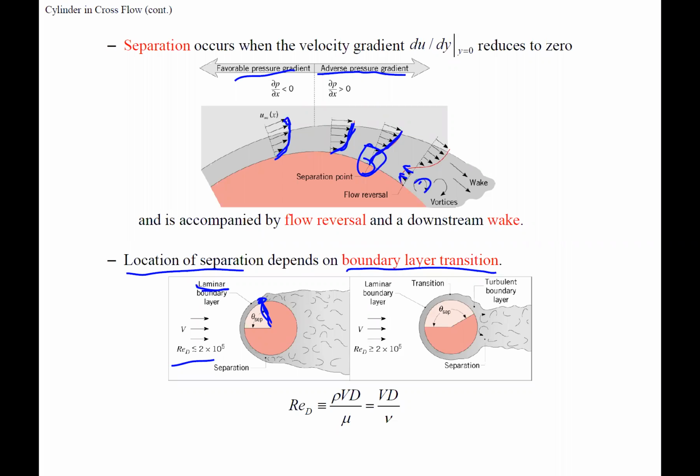So we get separation. Where turbulent has much higher velocities. So now we don't get separation so way over here, okay? So now that momentum of that fluid is much greater, and so separation takes longer to occur because it has more momentum. Okay? So these characteristics change your friction factor, your drag coefficient, your convection coefficient, right?